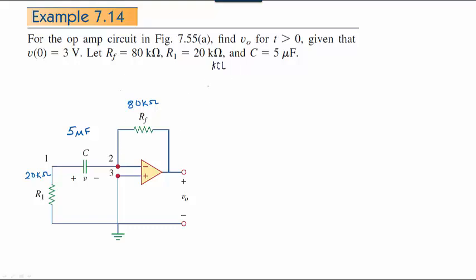So we're going to do KCL to analyze the circuit, and we're going to do the full first order differential equation glory here. I have a node here I can analyze at, and I have a node right here I can analyze at. Let's analyze KCL at node 1. We are going to say current out of the node equals current into the node, and when we've established our current flow directions, this would be voltage at 1. We have to be consistent in our arrows here.